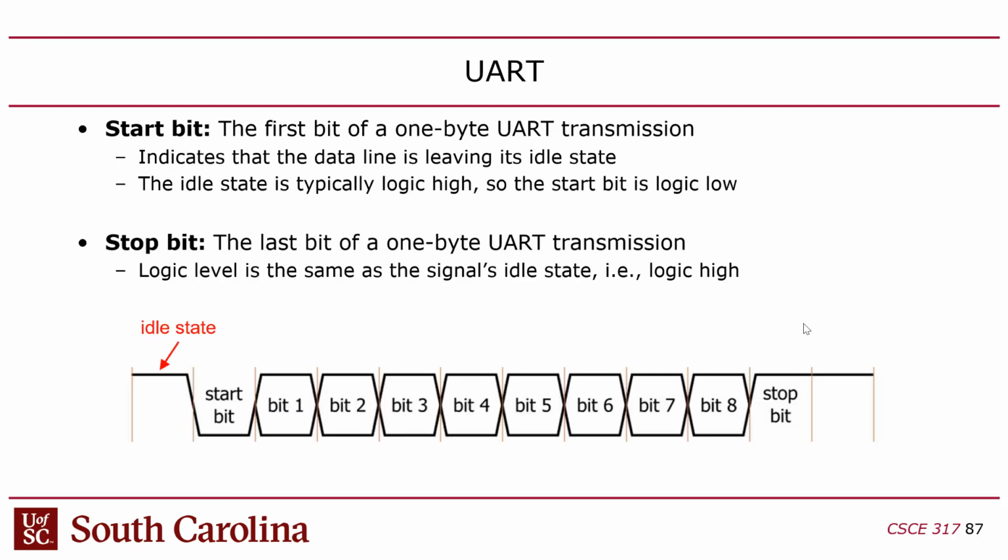So UART is also a serial protocol, because the data bits flowing in either direction are 1 bit wide. UART, though, is typically sent from least significant bit to most significant bit. So when you read a timing diagram, and that's usually the case with UART, you have to reverse the order of the bits from left to right.